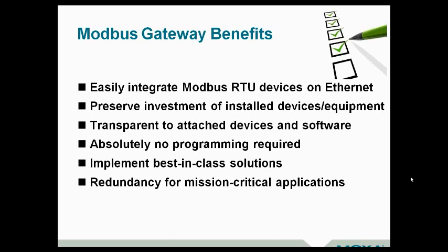It's really a drop-in networking solution that doesn't take any programming, and it gives you the option to find the best-in-class solution, right? So you can pick the best gateway out there that addresses your needs and fit that with your preferred control solution. For example, maybe you've got experience doing Modbus TCP. It lets you do a best-in-class solution for this. And one part that I didn't have a lot of chance to go into is redundancy. Understand here that the gateways will actually support multiple hosts talking simultaneously to that shared serial asset.